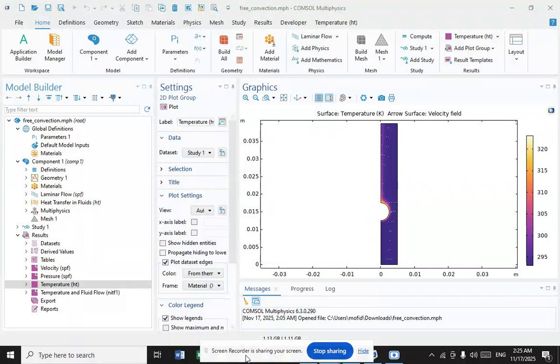The concept of a boundary layer is far more complex for free convection than for forced convection, because thermal and hydrodynamic problems cannot be treated separately, due to the fact that fluid flow is completely determined by heat transfer. The main motive force, the difference between wall and surrounding temperature, noticeably manifests itself only in a thin near-wall zone. This region of a temperature field with a thickness of σT is called a thermal boundary layer. The difference of temperature in the boundary layer creates a volumetric buoyancy force which causes motion.